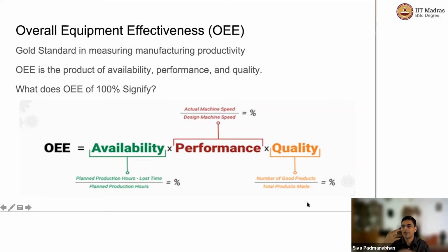If your maintenance, for which you are already given a shift at the beginning of the week, was done really well, you should not have lost time because your plan should be equal to your actual, and your availability will be 100%. But in reality, these things happen, so your availability will be less than 100%.